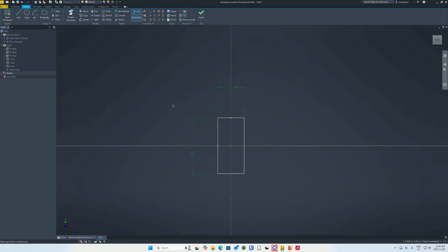And then the second part was to make this a square. So we can use the, not the parallel, but the equal. So we can go here, we can select this line, and we can select this line. Oh, it didn't like that. Adding this will over constrain. Cancel. Huh. Okay. Oh, because we've, yeah, we set that dimension. Okay. Let's hit OK. Let's get rid of this dimension.